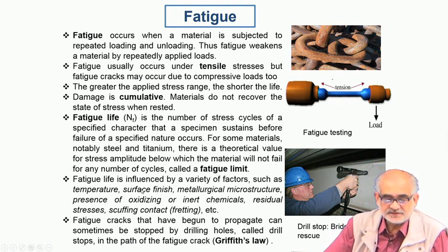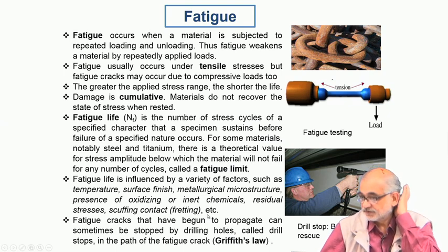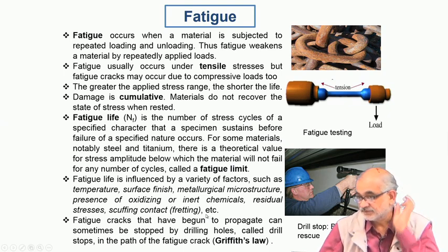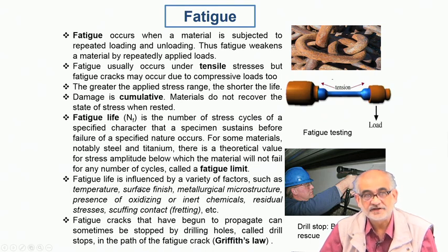Similarly, fatigue limit or life is also influenced to a large extent by the temperature, surface finish, the microstructure at the surface, the environment, and also the kind of residual stresses which are existing on the surface. And in case of such fatigue crack growth, one can invoke the Griffith's law and understand that if there is a sharp crack which is opening up onto the surface somewhere, if you create a circular hole in front of it, then you expect that the crack growth will be arrested.